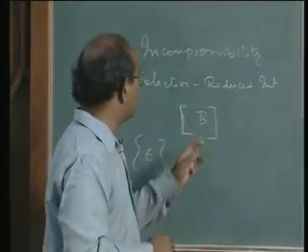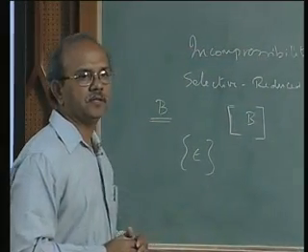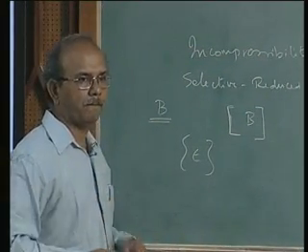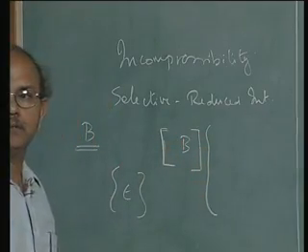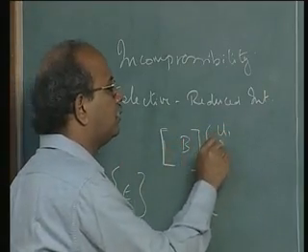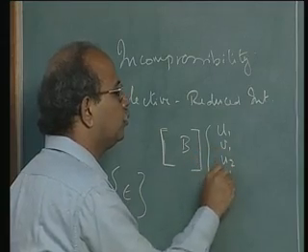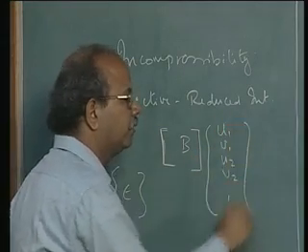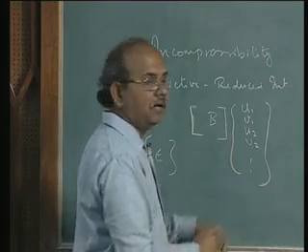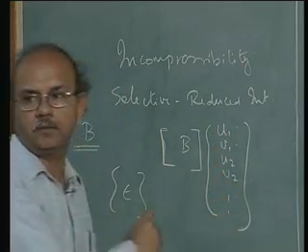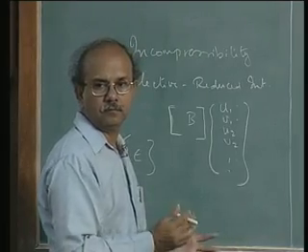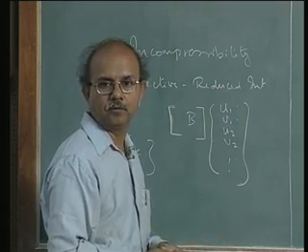The next one, what also is important, is the order in which you write U. You can write U in different orders. So for example, you can write this as U1 V1, U2 V2, and so on, and call them as U1 U2 U3 U4 U5 U6 U7 U8, for say a 4 noded element.